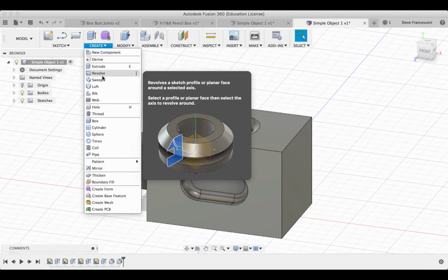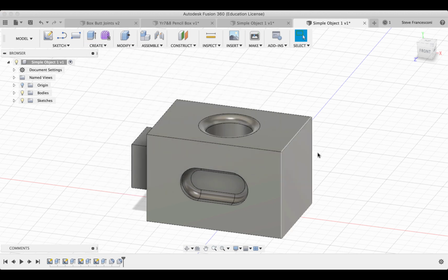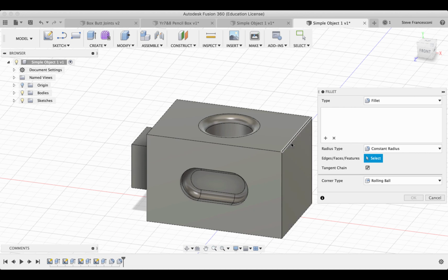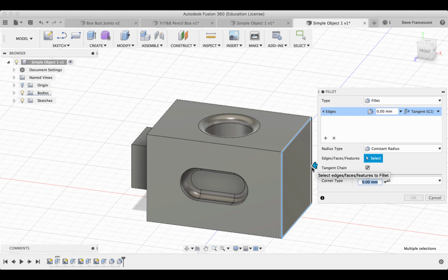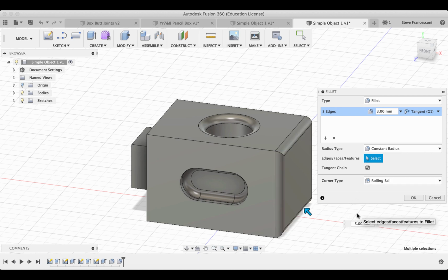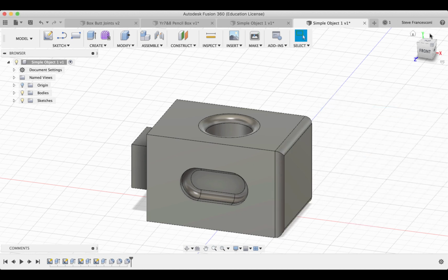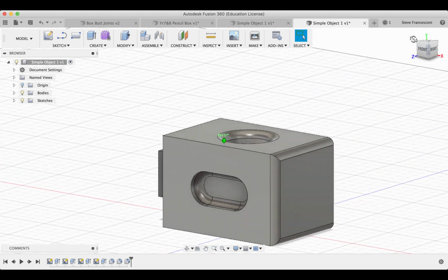Create a, go the wrong one, fillet on the edges up here, I can select this edge, this edge, this edge, this edge. Oh, did I get it? That one. And then it'll say, well, what size radius do you want to, I can put a 3mm rounded edge on that, or bigger. I think I'm just doing 3mm on this one. Done. All right, there is our object.